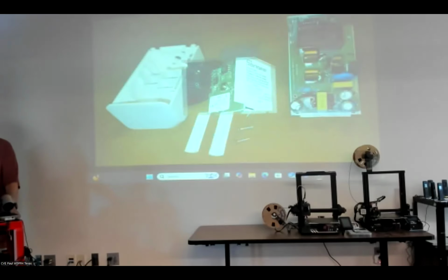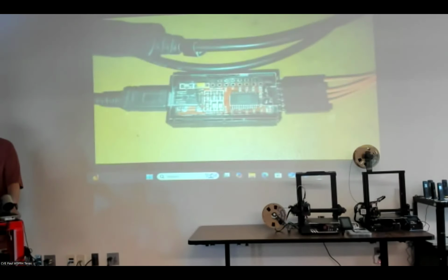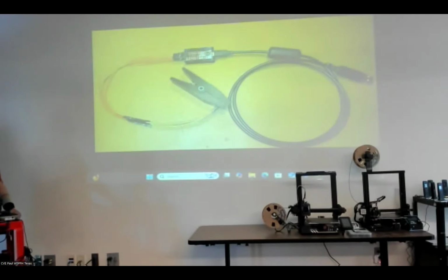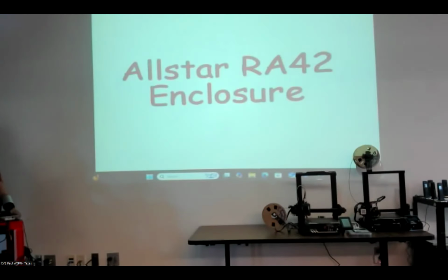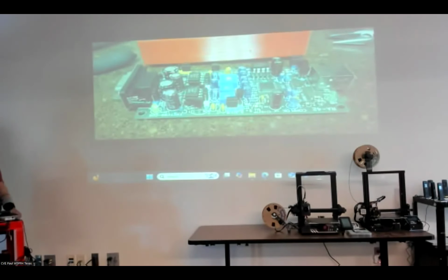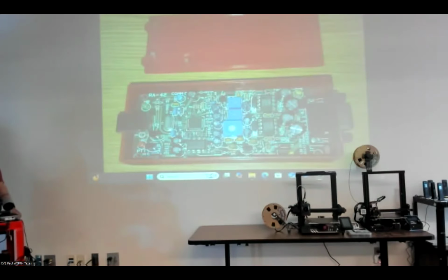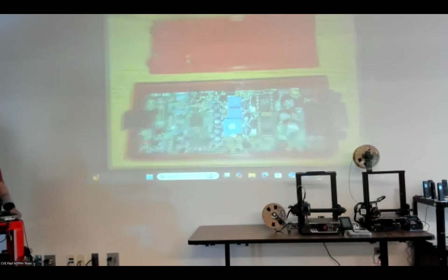I've seen people at the library buy some of the cheap filament, and the biggest problem they have is the filament getting wrapped on the reel, and it stalls the print. And then you gotta get in there, feed a bunch off to get it untangled. Right. Get it back on. I've never had a problem with feed issues with the Overture brand. I've had one spool of Creality before where it was wound wrong, like you're saying. And what that will cause it to do is when it goes to feed off, it'll actually tie itself in a knot on the spool.